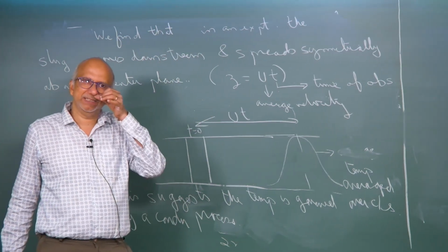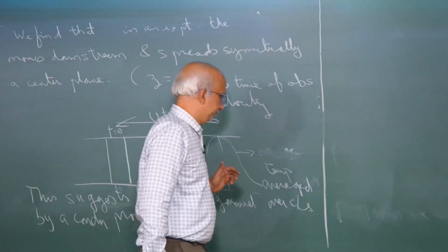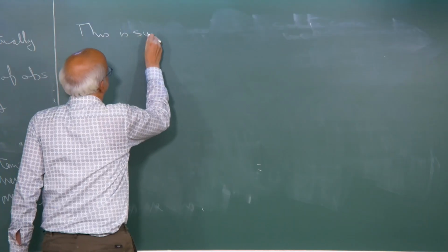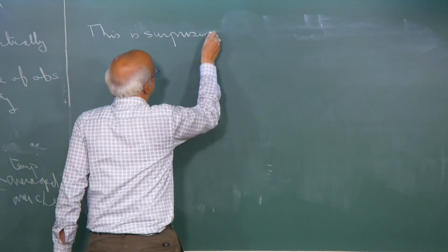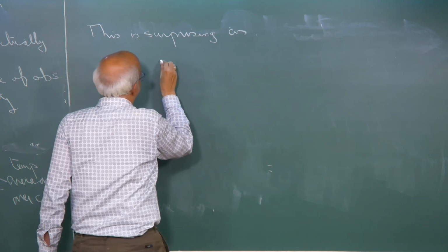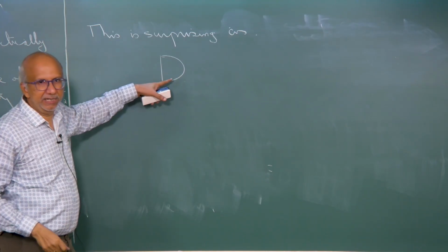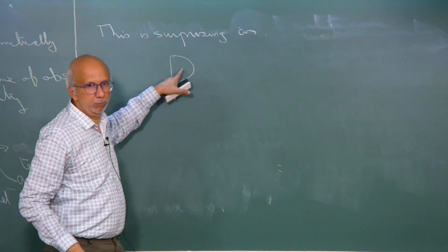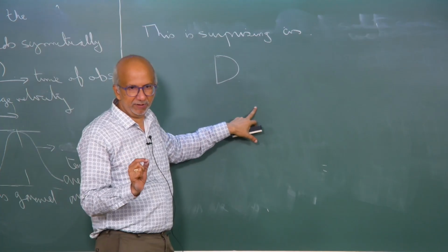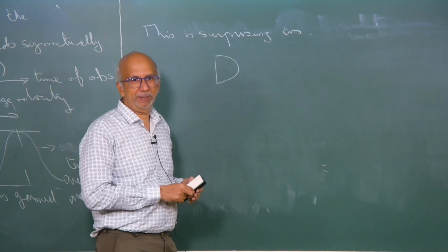Now, why is this surprising? What do you expect? Because of the parabolic profile, the slug at the center of the plane will move much more. The fluid near the wall will be stationary, just sitting where it is. The one at the center is going to move.